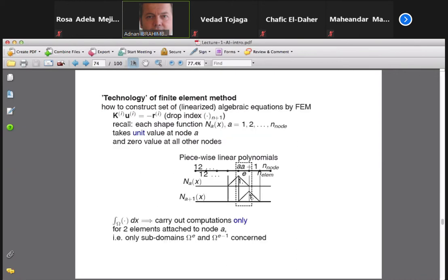And this is like a series production. Instead of worrying how to produce each and every element in a very special way, with very special coordinates, very special shape functions, and so on and so forth, I'm saying that all the truss bar elements, which have only two nodes, no matter where they are placed in the real structure, can be treated in exactly the same manner by using this natural coordinate transformation. This allows me to really simplify the computation and make it very efficient, because I keep turning this into the same part of code. Typically, it's called a subroutine or function.